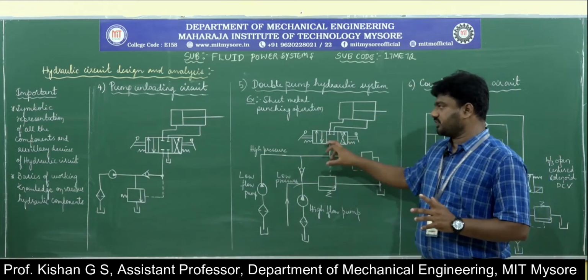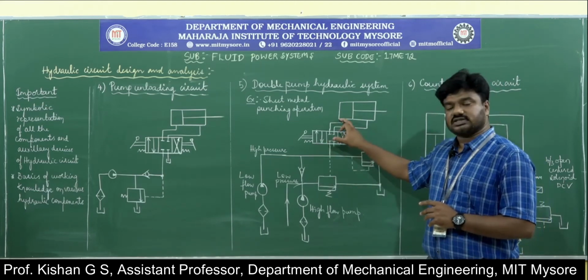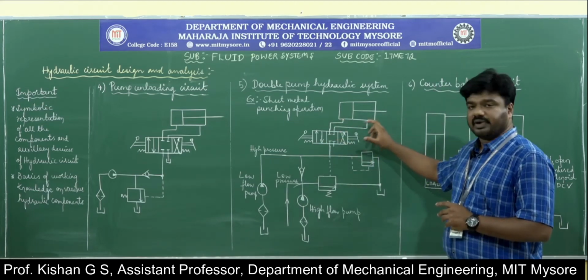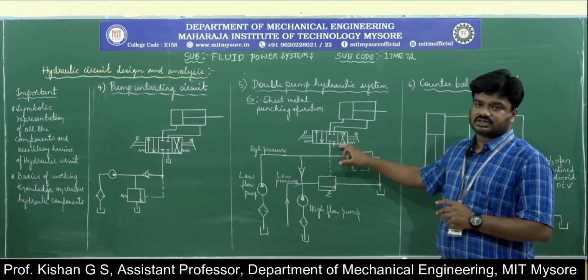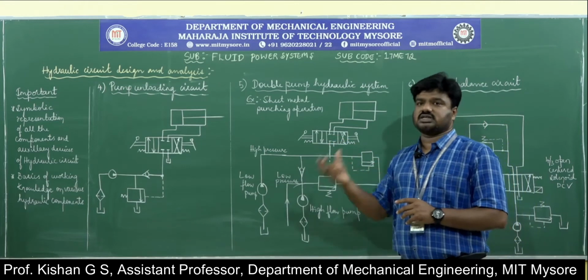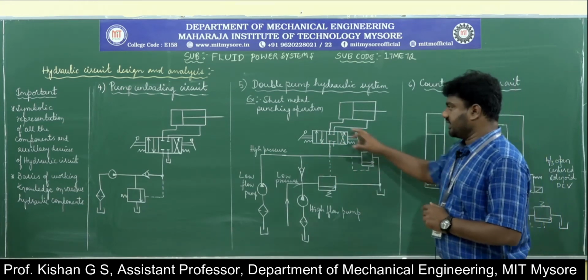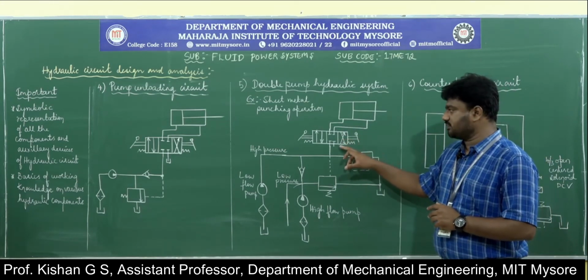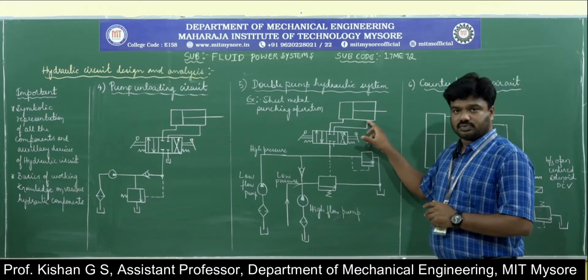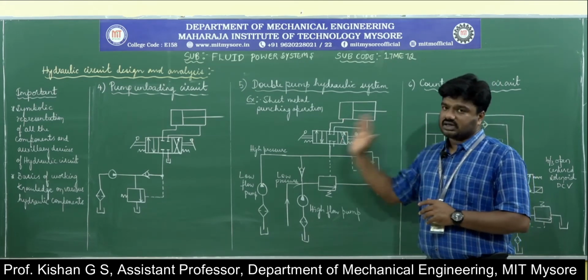In the first position there is a flow from the system pump to system port A and simultaneously from system port B to the tank port. In the second condition, the center off condition, there is no flow taking place, hence it is the waiting time or delay time in the operation of the valve. Next comes the third position, wherein there is a flow from the pump port to system port B and from system port A to the tank port, that is in the retraction.